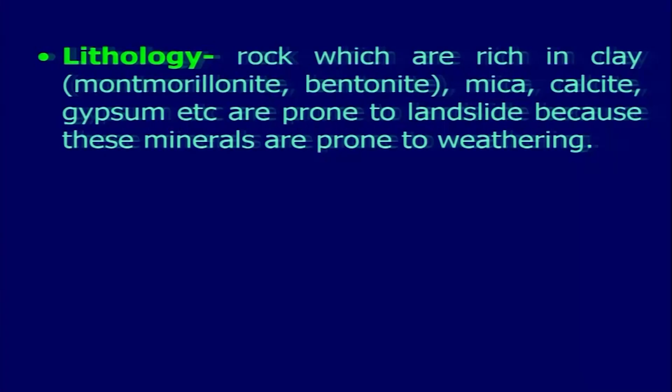For example, take the lithology: rocks which are rich in clay minerals like montmorillonite or bentonite, and if you are having mica, calcite, gypsum, etc., are prone to landslide because these minerals are prone to weathering.